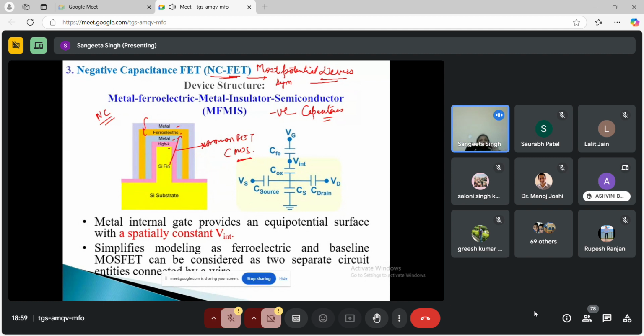A negative capacitance behavior will not be stable. A system having only negative capacitance will not be a stable system. So what does negative capacitance mean? Say you are having 1 volt here and you are having a ground here. Ideally, what happens to this capacitance? The electric field starts from positive and ends at negative, and this is the positive C behavior. So if you are having 1 volt here, there will be some loss, and whatever is reflected or mirrored here will be lower than 1 volt. This is the classical capacitance behavior.